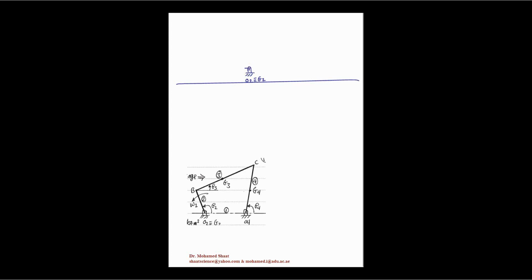So initially we're just gonna draw any light line, very light line in this way, and over this line we're gonna measure the distance O2, O4, which is already given as 70 millimeter in the main problem. So 70 millimeter, it means that you're just gonna measure 7 centimeters starting from the O2 point. Then you're gonna mark another point to locate the point O4. Then you're just gonna draw the support and connect these 2 points together. We're gonna end up with the first link.